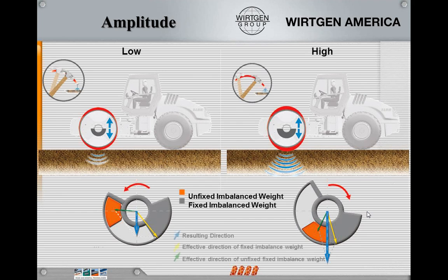Now the other one, we can switch it in the other direction and slide that weight towards the mainstay weight, and we have more weight on one side, making a higher hammer or heavier hammer hitting. So we have a high impact or high amplitude. But with that high amplitude, we can't spin as fast, so our frequency isn't as high.